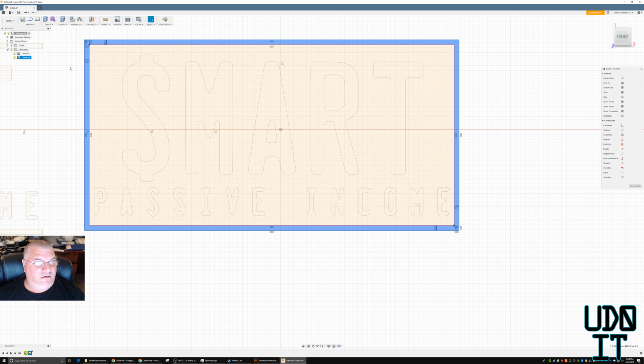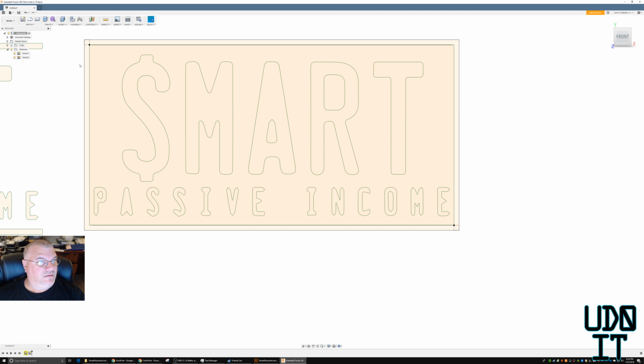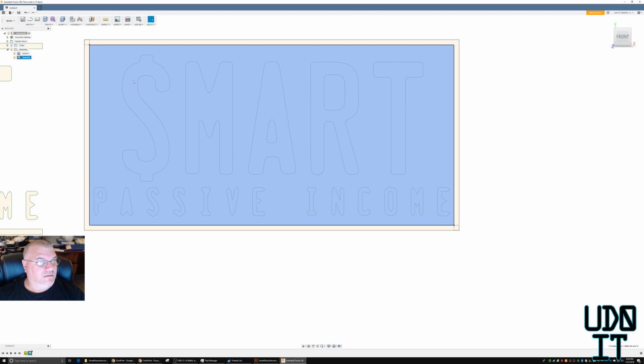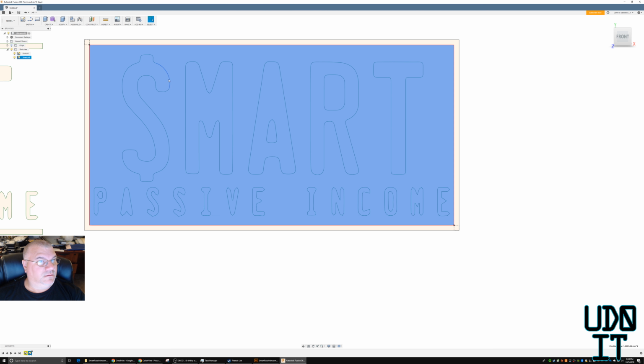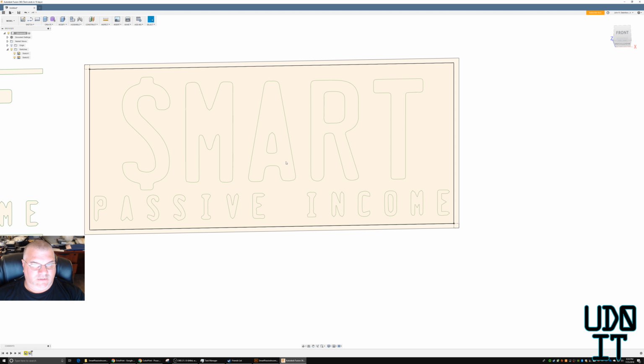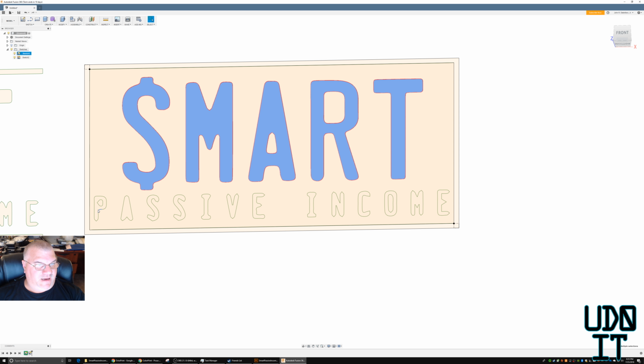So I have a solid area here, and it's these areas here that I want to extrude. So I'm going to stop sketching so I can select, let's see, I need to select this sketch. Being rather difficult right now. When you hover the cursor over, you have to make sure it changes a slightly different color. You see all that flashing going on? And once it changes a slightly lighter color, then you know that that's the region that's going to be selected.